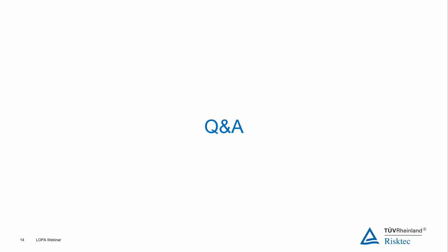Yeah, so the way I like to do it is to say the PFD is what it is, but then demonstrate at the bottom of that that with the implementation of recommendations X, Y, and Z, this will bring the level down to the TMEL or below the TMEL, or whatever level it's going to bring it down to. So I like to quote it as it is, but with the caveat that with the implementation of all of these recommendations, we get it to below that.